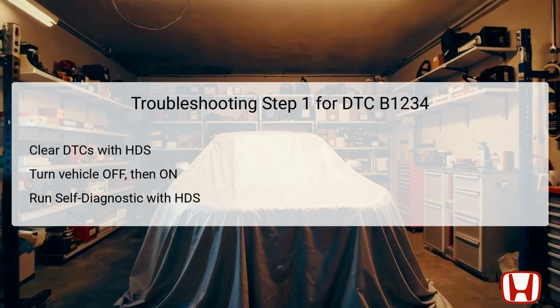The initial step in troubleshooting DTC B1234 involves using the Honda Diagnostic System, HDS, to clear any stored diagnostic trouble codes. This process resets the system, allowing technicians to verify if the issue reoccurs. After clearing the codes, the vehicle should be turned to the off lock position, then switched back to the on position to enable diagnostic functionalities.